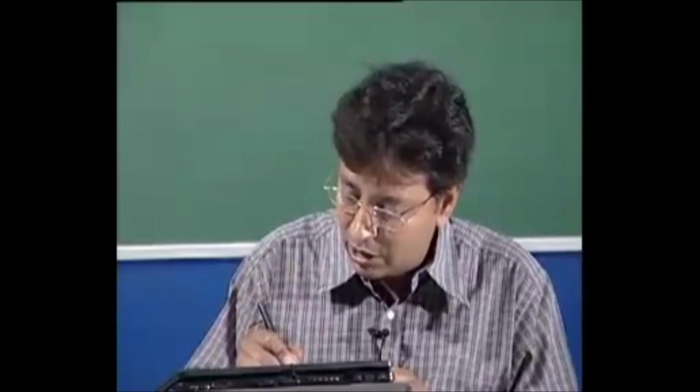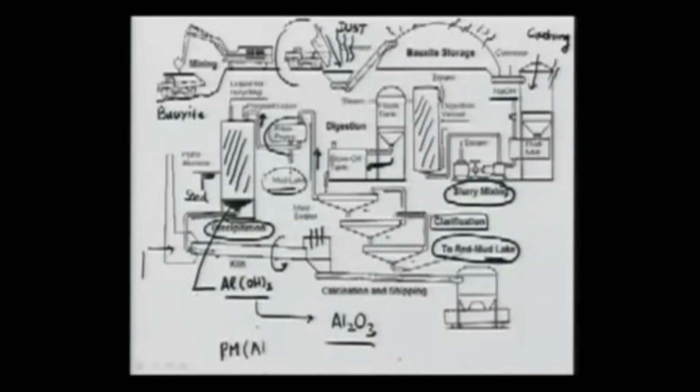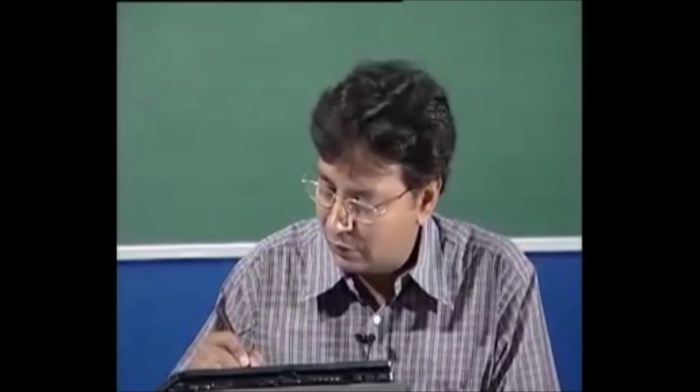Okay, so there will be particles that will be largely, let me write in the bracket so that there is no confusion, Al2O3. Then it can also produce a significant amount of SO2. Why SO2? Because the fuel oil or the furnace oil that we are firing will have sulfur, and that sulfur will be burnt out as sulfur dioxide. So you can see sulfur dioxide.